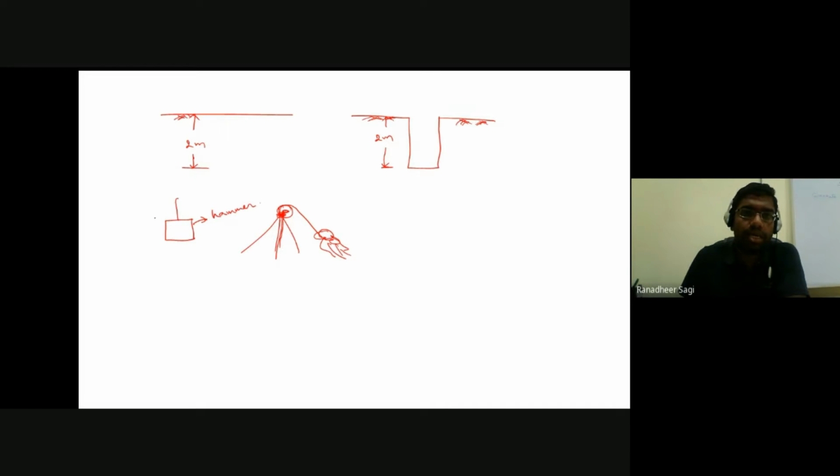It's a standard hammer of mass 63.5 kg, and this hammer in turn is connected to a guiding rod so that it can slide over this guiding rod. It can be lifted with a sliding mechanism, where this guiding rod is going to guide the hammer in which direction it is going to be lifted, and so on. Because the hammer should not be swinging, it has to be properly lifted and released, properly lifted and released.